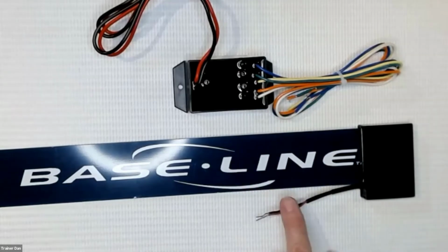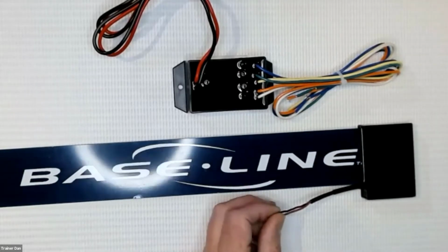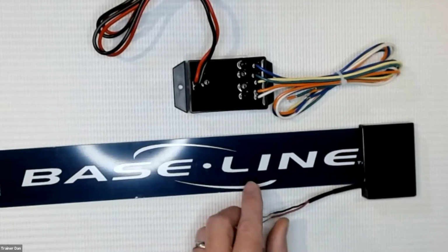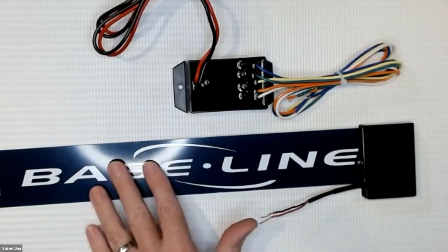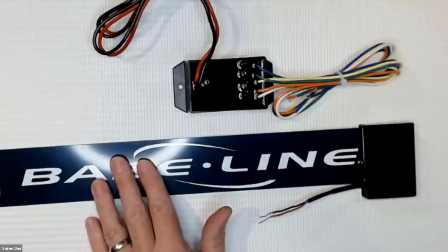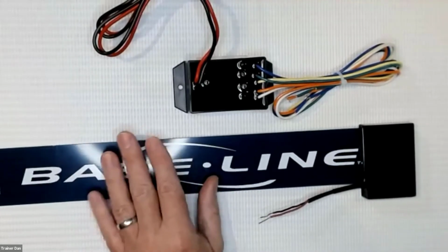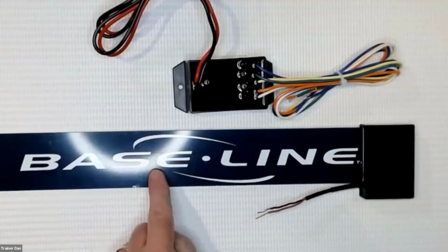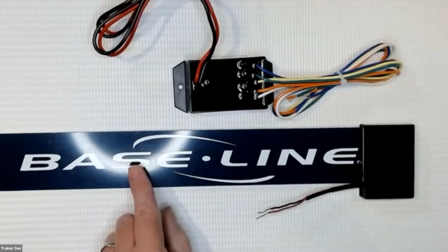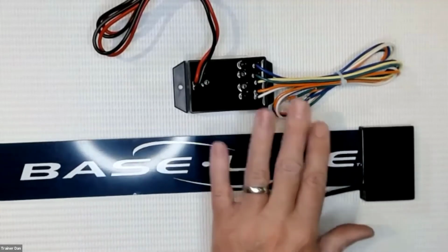On the soil moisture sensor, we could have a moisture reading problem. We could have a temperature reading problem. And it could be because perhaps this blade got damaged by a device, or that the wire's broken. Perhaps a tractor damaged this and it's allowed moisture into this one. So we can find that information out on this one.